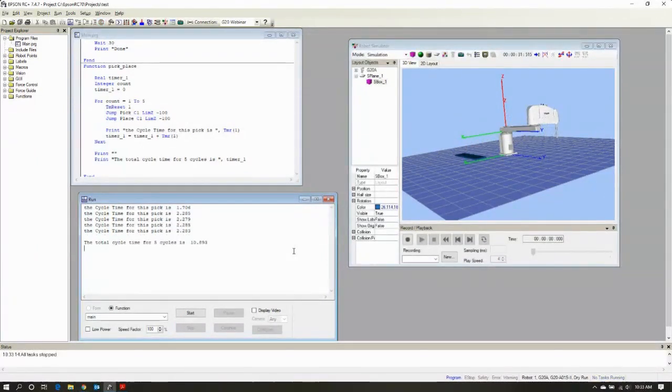So now you notice by adding that, we've now gone from 14.85 on just the pure jump to 13.08, adding the LIMZ. Now we've gone to right at 10.9. We've picked up an additional little over 2 seconds of cycle time just by adding the arch. So we're getting more efficient. Again, we're not changing the speeds, we're not changing the accelerations, we're getting more efficient in our movements.